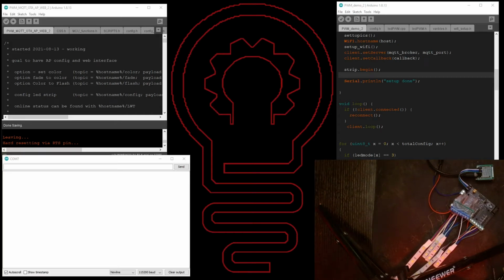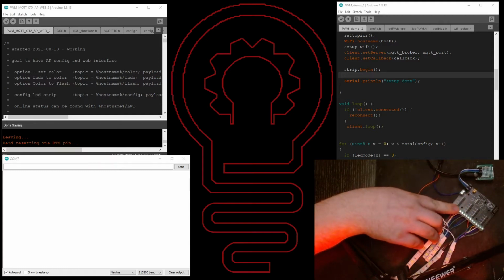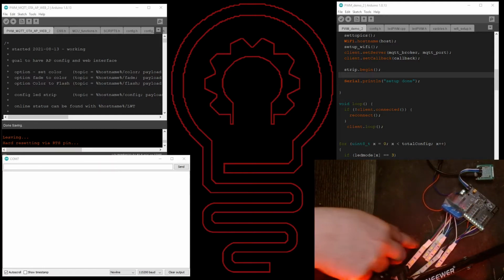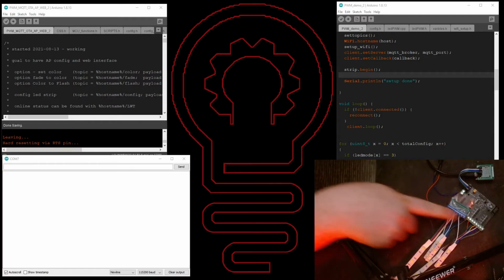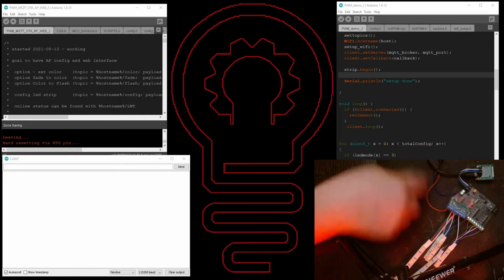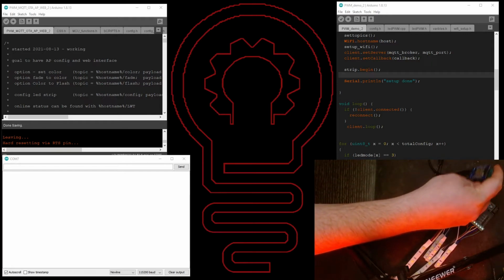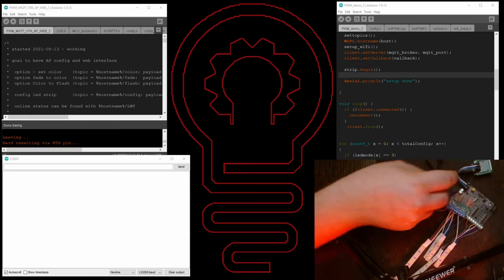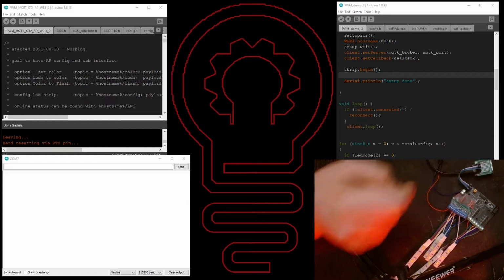In this video, I will be demonstrating the PWM LED strip controller. In my example I have the circuit board here. I have 5 different strips connected, and I have a power terminal strip that is taking in the 12 volts and separating it for all the LED strips, and we have a Wemos D1 Mini and a makeshift shield connecting it through the I2C IDC connection and this ribbon cable.